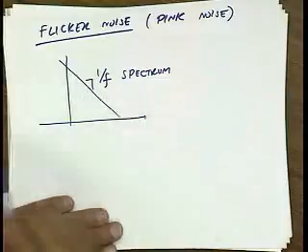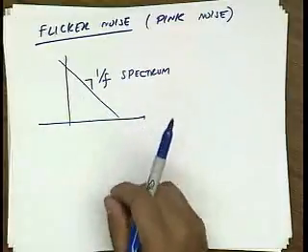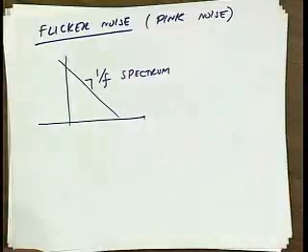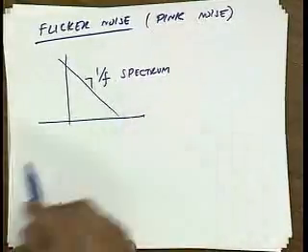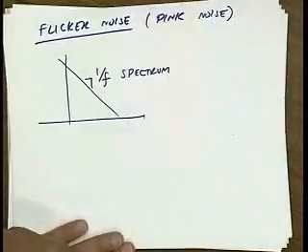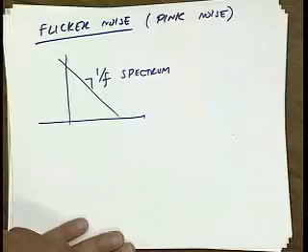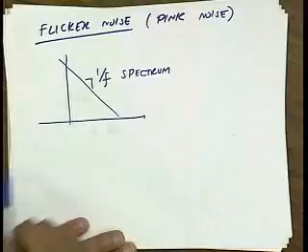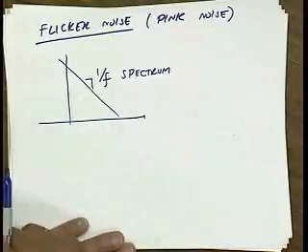This kind of noise does have this strong self-correlation. It's a very low-frequency phenomenon. And the origin of flicker noise in some ways is not very well understood because lots of different things in nature actually do produce a 1 over f noise spectrum. Which one in a transistor actually leads to 1 over f noise is somewhat controversial.